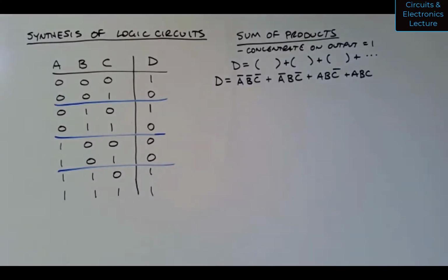For example, you have maybe a temperature sensor on the engine, and you have RPM, and you have a bunch of other sensors on an engine, oil pressure, water, maybe just different values. What I would do is first create a circuit, if you care about whether the engine is running, that uses all of those inputs to create a Boolean variable that is the engine is running. So I'd reduce the problem down into sub-circuits instead of trying to handle it all at once.